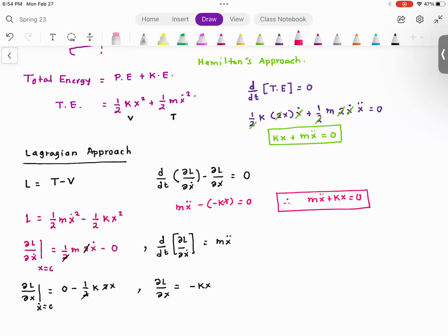So when we are going to solve the robot arm, here is what we are going to do. Whatever the dynamics of the robot, we will solve the forward kinematics problem completely. Once we solve it, remember we talked about finding the velocities. We'll find the velocities and the total kinetic energy for the robot, which we will treat as T. Then we will find V, the total potential energy.